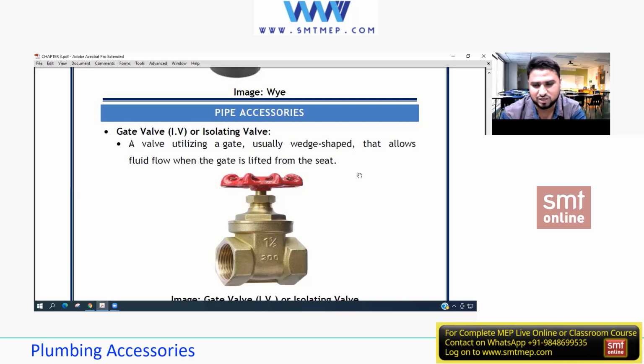So it can be partially open or partially closed, but not recommended. Because of the gate valve's flat surface, the flow directly hits it, damaging it. But with the curvature of the ball, we'll have somewhat regulative action, though again not recommended. That's why they are using it nowadays, because its life is more compared with that. So that's why nowadays we use ball valves rather than gate valves.